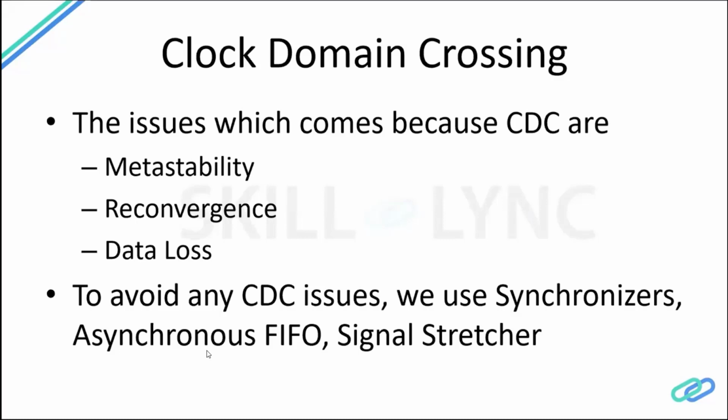So the best way is we add them in an asynchronous FIFO. What we do in an asynchronous FIFO is we take whatever data we have to transmit from one domain to another domain, and put all that data in the FIFO, write with the clock from where we are sending the data, and read with the clock of the destination. So using this, we use the asynchronous FIFO.